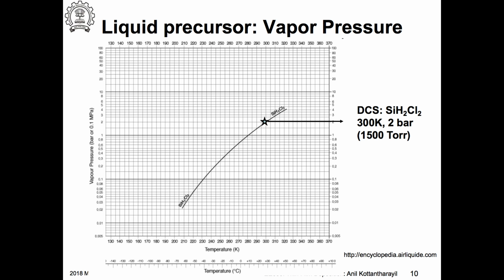In the initial stages we had a lot of trouble, because every time we did this process, the sheet resistance of the emitter diffusion would be different. We were not getting controlled sheet resistance. The assumption was that the clean room where this whole thing is placed has fairly well controlled temperature.